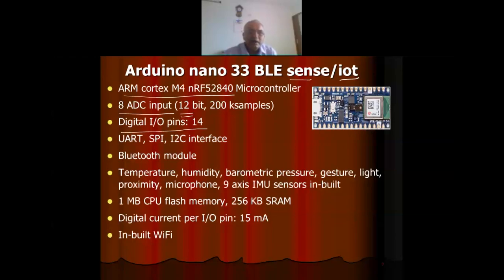And it has UART, SPI, and I2C interfaces. UART means Universal Asynchronous Receive Transmit. That is a serial communication protocol. SPI is another serial communication protocol known as Serial Peripheral Interface. And I2C is also a serial communication protocol known as Inter-Integrated Circuit protocol. So these three interfaces are also provided with this.